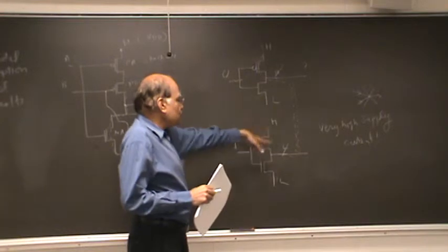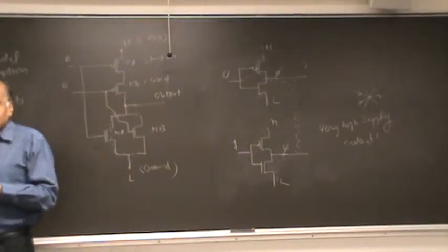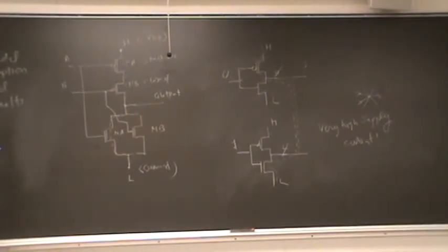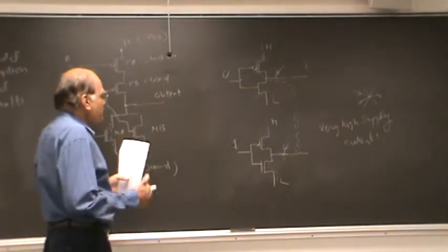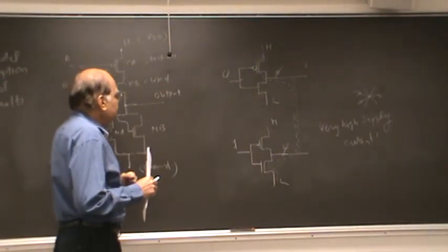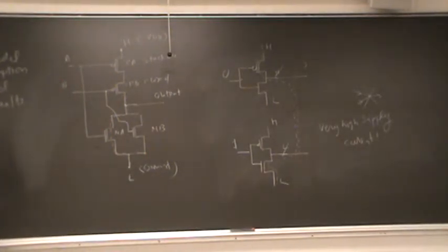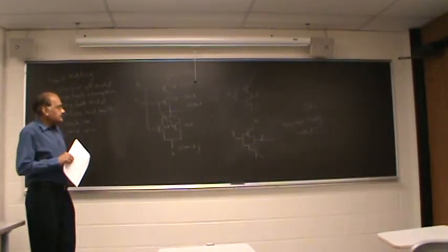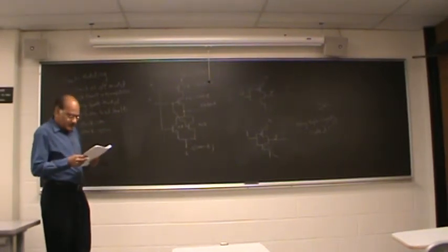So as long as the two values shorted are of opposite value, this would be detected, provided you are monitoring the supply current. As I was mentioning, people now regularly test the chips for very high supply current. And it is highly effective for faults of this type.